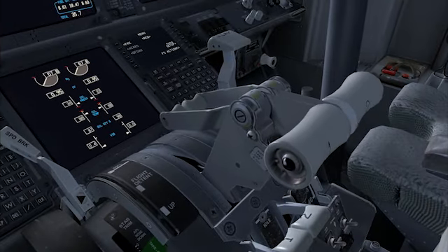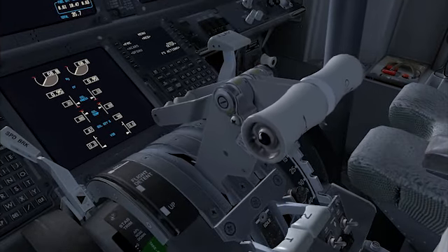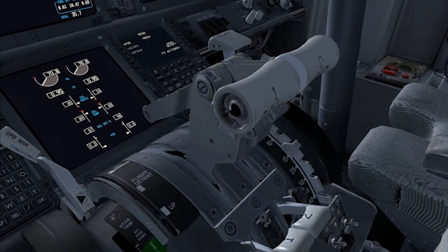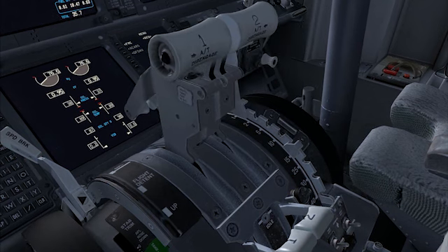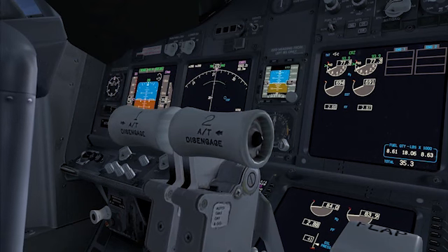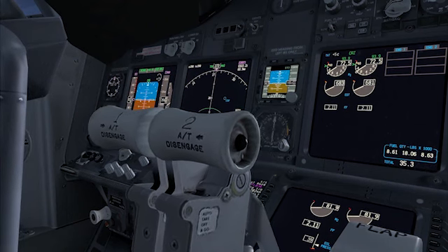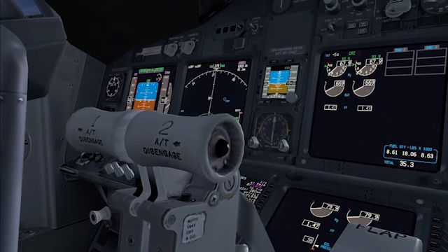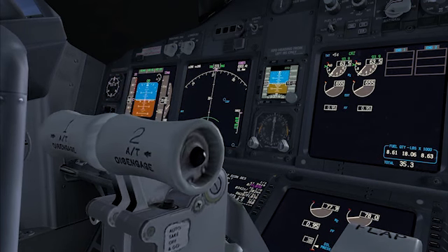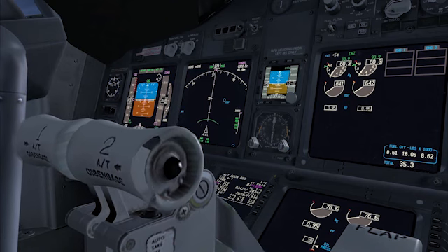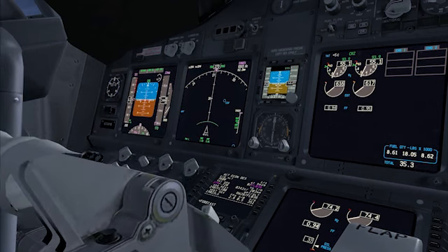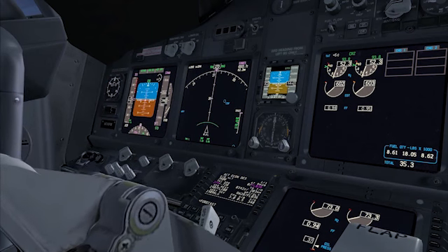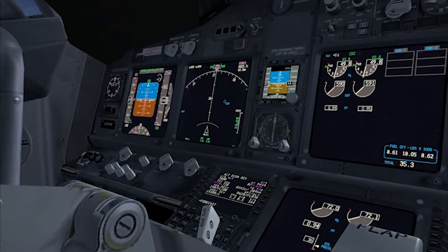Now onto the subject of auto throttle, our final subject. The auto throttle is tightly integrated with Autoflight to ensure that by whatever mode the pilots wish to operate in, selected of course on the MCP, the flight control computer A, in this case, and the auto throttle computer can send commands for thrust output. All commands from the auto throttle computers move down the line to eventually show the physical movement of the thrust levers on the control stand, in addition to showing indications on the displays that reflect the thrust being output by the engines.